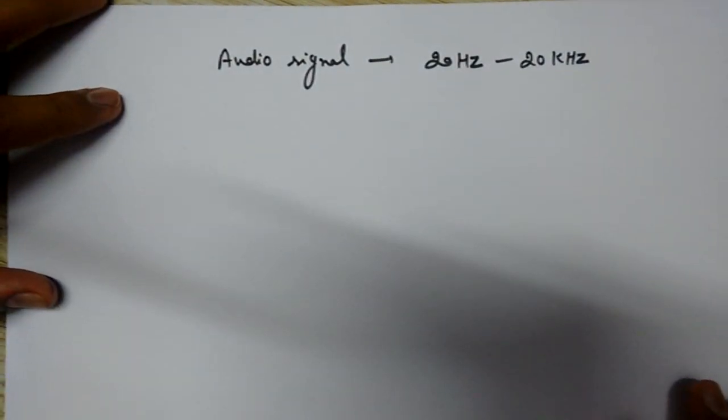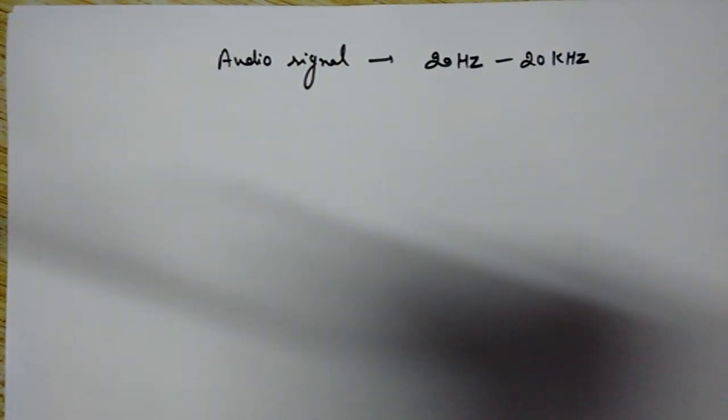This is the range of audio signals. So without modulation, the transmitted signals of all stations will get mixed up. But by shifting these message signals into different frequency ranges by modulation, this problem of interference can be solved. Now let's come to another benefit of modulation, the second one, which is the practical height of the antenna.